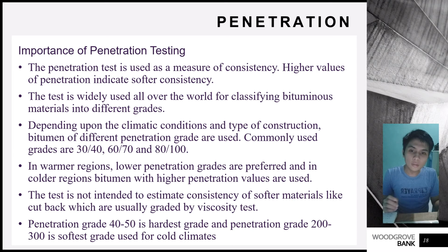So, to understand the importance, or the value or purpose, of penetration testing: the first reason is that the penetration test is used as a measure of consistency. Higher values of penetration indicate softer consistency. This test is widely used all over the world for classifying bituminous materials into different grades.